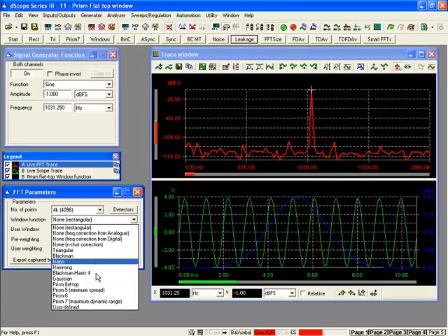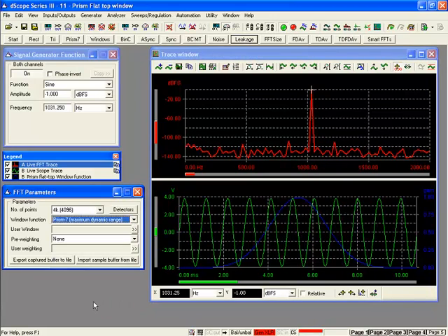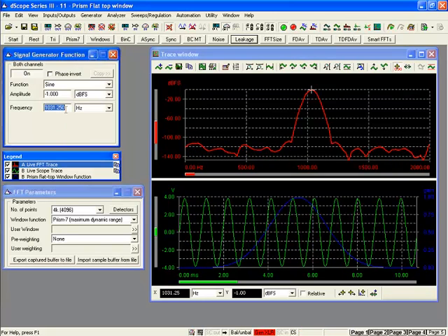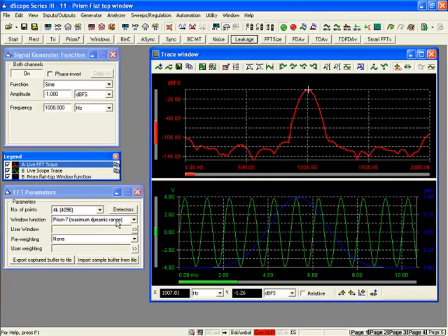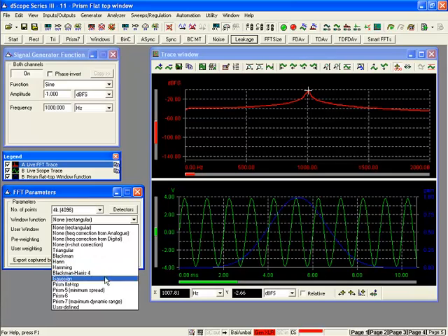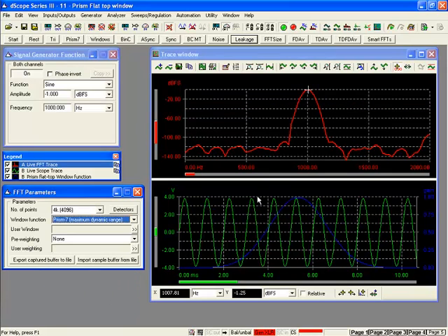Now, if I switch to a Prism 7 window function here and change to 1K, so we're talking about an arbitrary tone frequency of 1 kHz for which we know we need a non-rectangular window function to make a sensible measurement. You can now see that the energy here measured in this bin, the nearest bin to 1 kHz, is now reading -1.26 dBFS. Now, this is not an error on the part of the test system because this is a very tightly toleranced, calibrated measurement system, but it's showing us 1/4 of a dB of error at the tone frequency, which is quite significant.